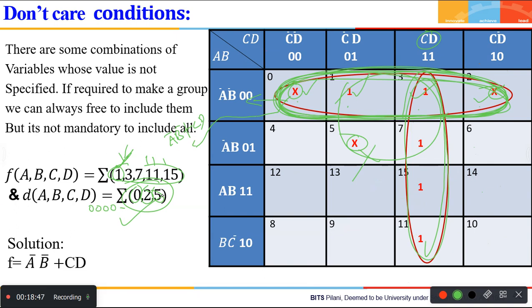Now, have you understood the concept of don't care? That means in that truth table, in that logic circuit, whatever combinations are mentioned as don't care are not a botheration at all. They are dummy inputs. It's not defined. It's as if not designed. Whether the output is going to be 0 or 1, you're not bothered about it. Have you understood? That's called don't cares.